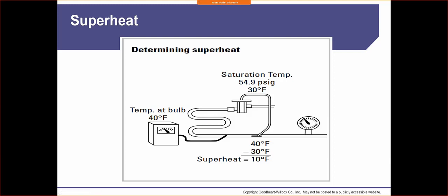But because we're blowing warm air across the evaporator, that refrigerant is going to want to turn into a vapor and stay in a vapor state, because we're increasing the temperature. That heat is being absorbed into the refrigerant. By doing so, we're going to absorb enough heat so by the time we get to the end of the evaporator where we take our measurement, we'll have a total of 10 degrees of superheat absorbed throughout the evaporation and cooling process right here.